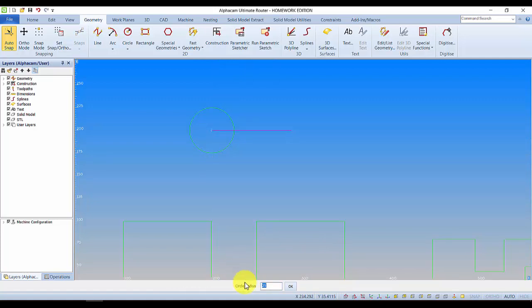To get another circle, the command is still open, it still says 25, so press OK, drop a circle at that end. We also need a pair of circles radius 10, so type in a value of 10, enter, and drop it on there, and another one. Dropping it on here snaps on. You could just as easily have typed in the coordinate, but I find it easier to just drag and drop it in with a click.